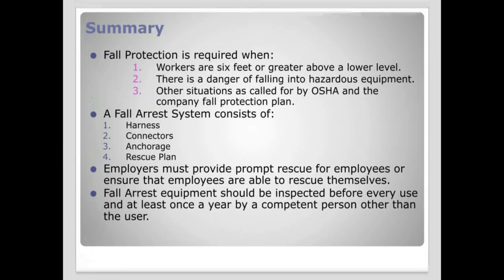In summary, fall protection is required when 1. Workers are 6 feet or greater above a lower level. 2. There is a danger of falling into hazardous equipment. 3. Other situations are called for by OSHA in the company fall protection plan.